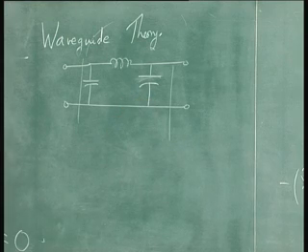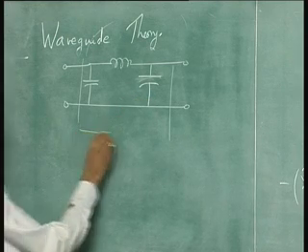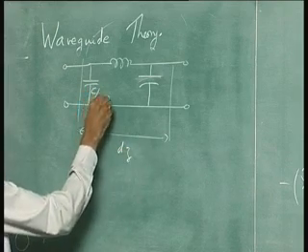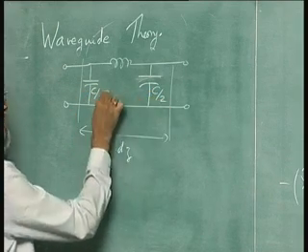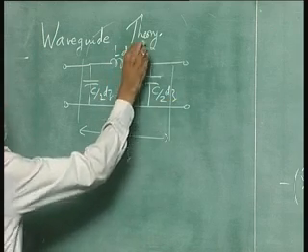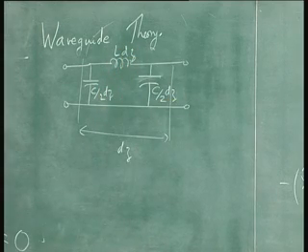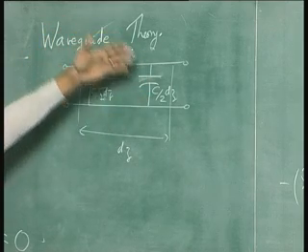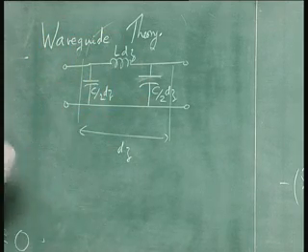an equivalent circuit. This distance would be dz, this would be C over 2 dz, and this is L dz. And you will be told that this represents the transmission line, an ideal transmission line for a short distance dz.